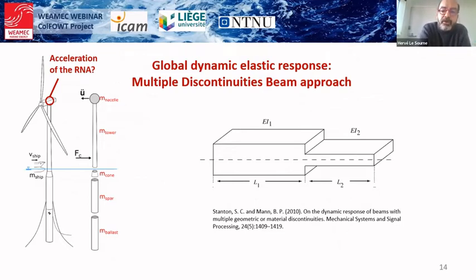Okay, so now, just after the collision, we know that an elastic shock wave propagates through the structure up to the nacelle. And so the issue is to estimate the level of acceleration at the center of gravity of the nacelle. And to do this, we base our developments on the multiple discontinuity beam approach, which was proposed by Stanton in 2010.